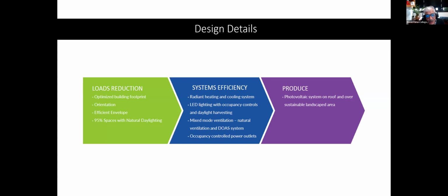Orientation of the building: it was decided on an L shape, because a major part of the building is facing west, so in the afternoon you have this sunshine, east and west. So you have the sun coming in, and you can take advantage of the daylight.